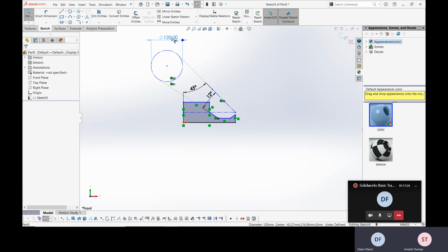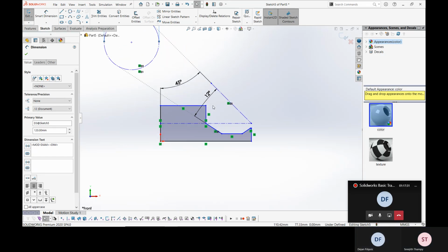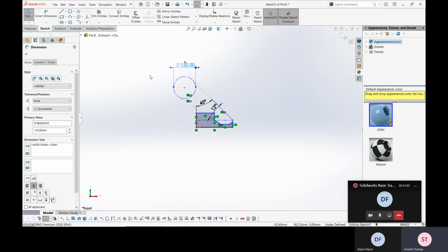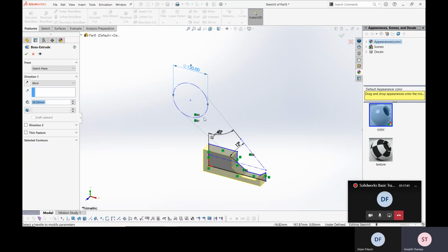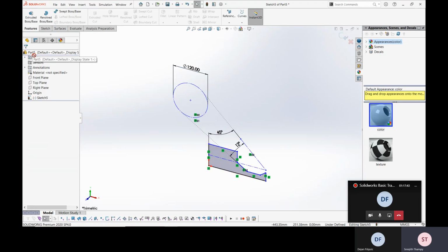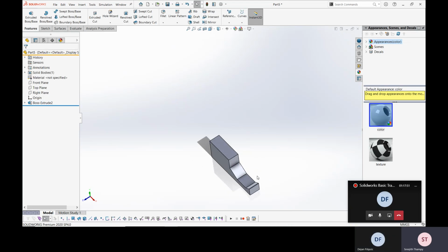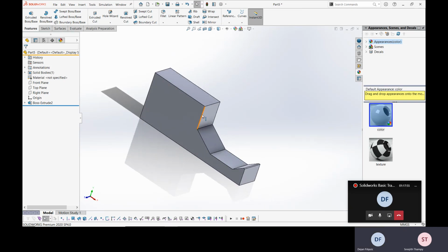See, I'm having a circle over here. There will be conditions like this, where it is tangent to this circle, and I want this line and this line, but they are not required in the actual model I need, but they are reference geometries. So when I extrude, my sketch is not affected by the construction geometries. See, only the lines that are construction geometries are ignored.